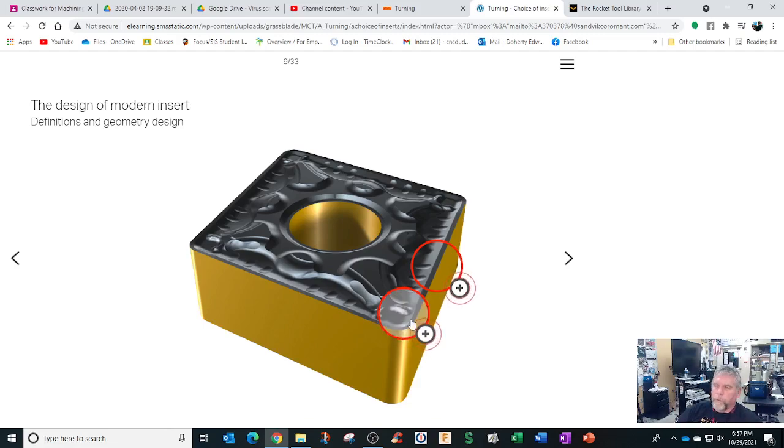That makes a big difference because when you do your curves and your chamfers, they may disappear or they may be overcut, and you won't even know it because it's hard to tell on those ones. If your CAD can't program it, you've got to actually be calling out the correct insert type. Make sure you use the correct insert in your machine.